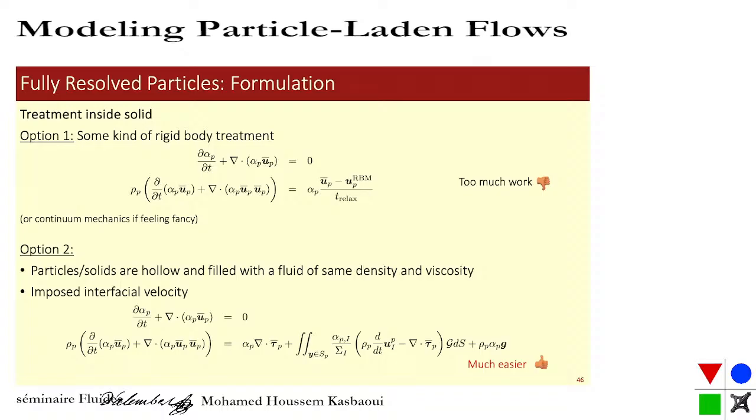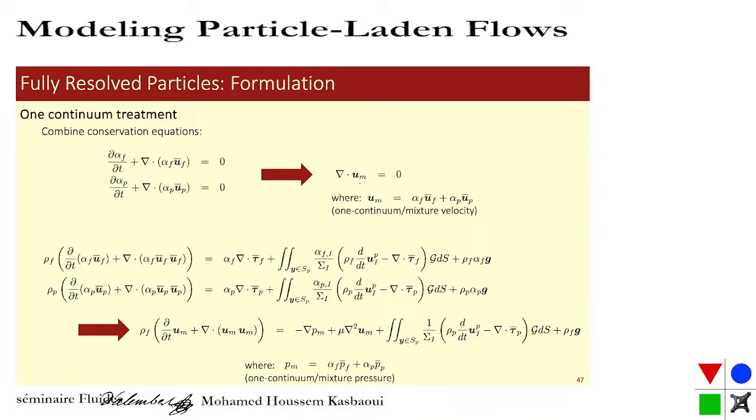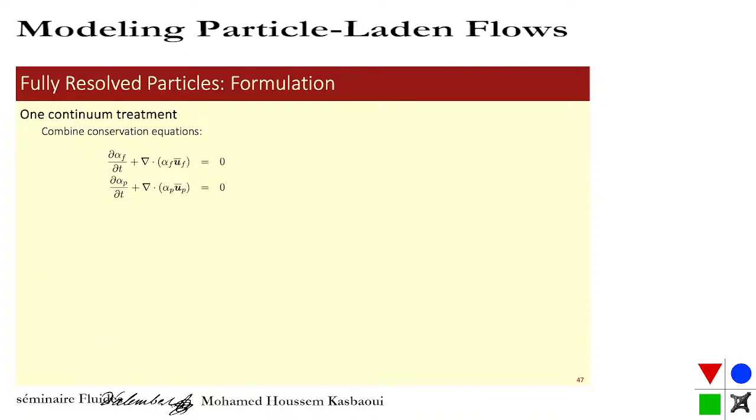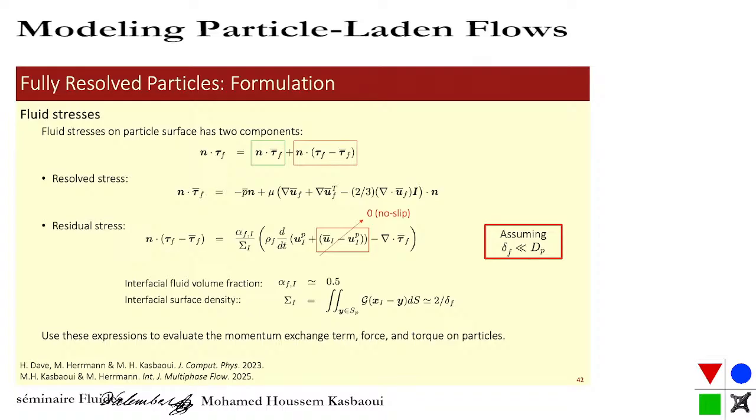So I think that you can put anything you want. I haven't really tested it. Anything you want, as long as it gets rid of volume fractions later in the equation, because dividing by volume fraction is where the issue stands. The one thing to keep in mind is that we solve these equations in terms of the mixture velocities, but to compute the drag on the particle, you still have to go to the slide here and use this formulation where you have a volume fraction and that filtered fluid velocity.